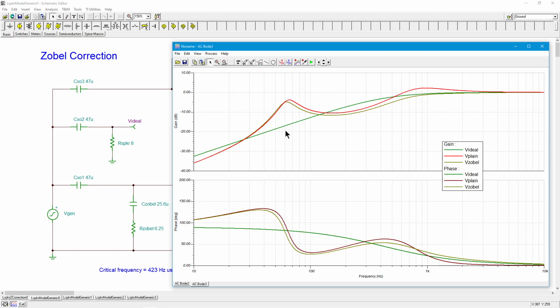All right. On the other hand, compare that untreated version to the ideal version. And up here, up around several hundred hertz, 1 kilohertz or so, there's a peak. There's an obvious peak going on here. And this is, again, because that impedance is starting to rise because of the voice coil inductance. So the amount of loss that we're getting, not so much. Let's see how big that actually is.